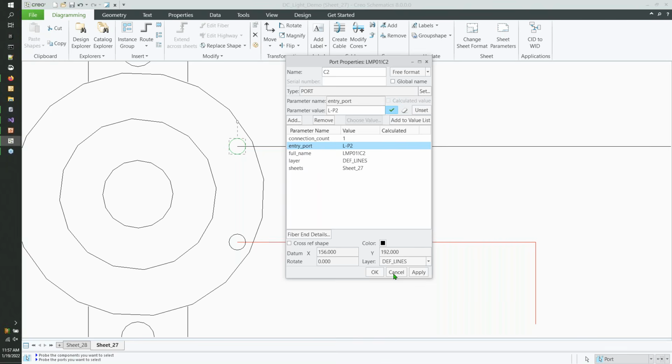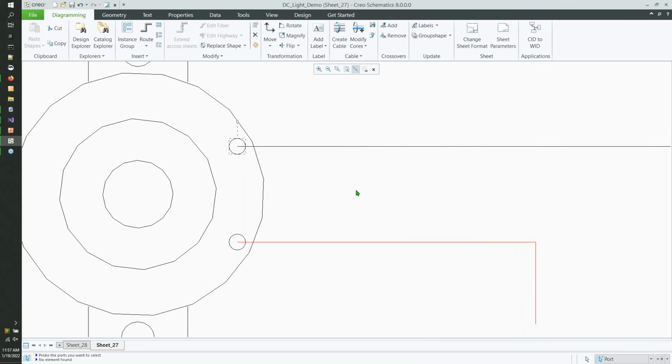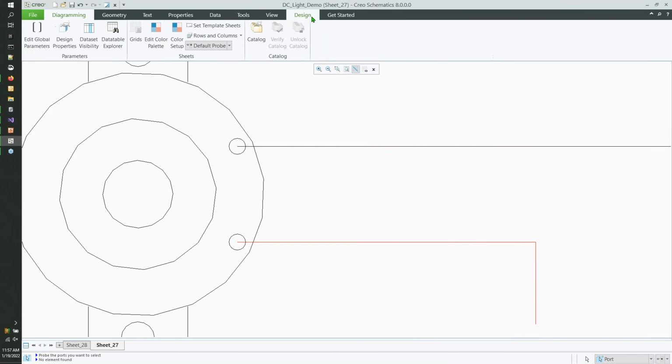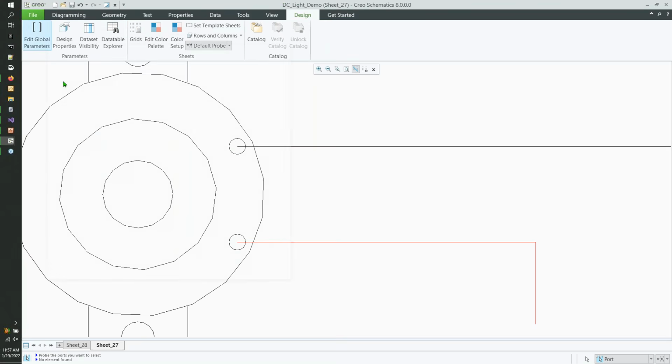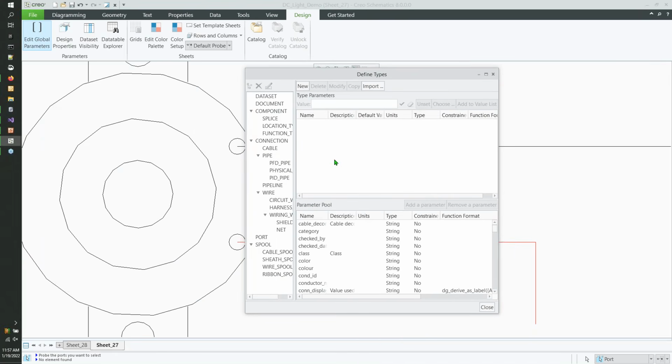So we see here that we've got some parameters that relate to naming. Now, these things can be facilitated on the design side by utilizing your global parameters functionality here within schematics. I've accessed the design tab and global parameters, and you can facilitate setting these things up so that these important things are part of your artifacts by definition. It's not like we're expecting you to go in there and add a model name parameter every time, every day, always, on every artifact.